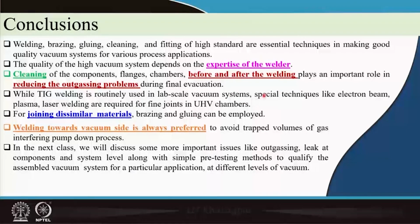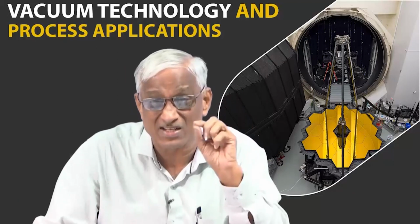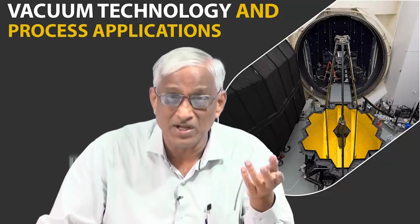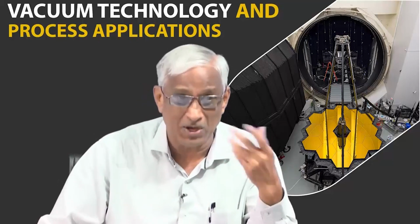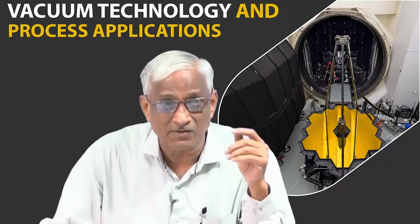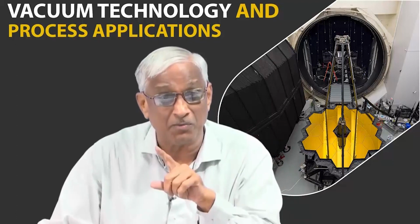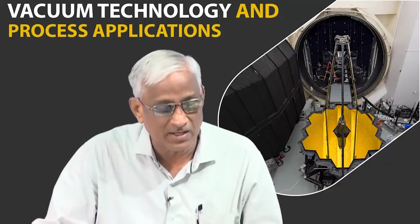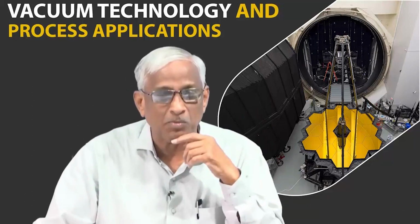So, TIG welding is mostly used, but ultra high vacuum requires specialized additional welding technologies. Initially use TIG welding, but when you use TIG welding, it may sometimes create dirt, and welding can be dirty. You should keep track of it. Even though it is not cost effective, you may have to use advanced welding technologies, because the final products are much more costly, like IC chips. So, it is a one time investment, no problem.